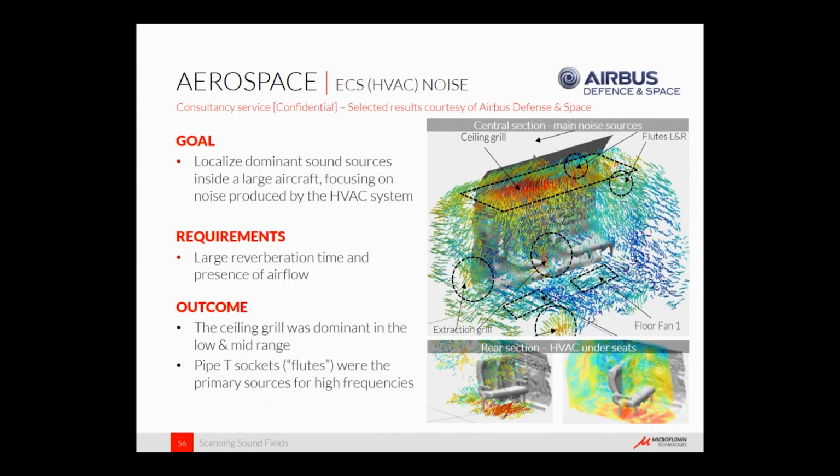So initially, sound was radiating at an angle from the surface and then bent down towards the perpendicular to the surface, towards the passengers sitting at the seat. And this was also in an annoying frequency range, like 2 to 3 kilohertz, and pretty dominant there.